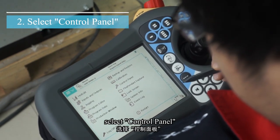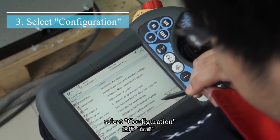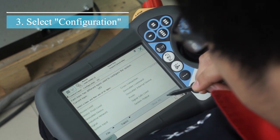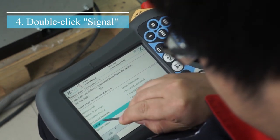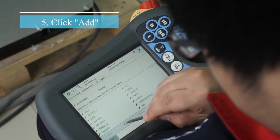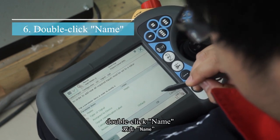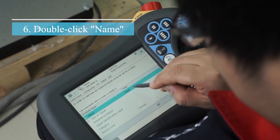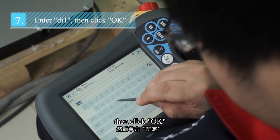First, click the Main menu button in the upper left corner of the FlexPendant. Select Control Panel. Select Configuration. Double-click Signal, click Add, double-click Name, enter DI1, then click OK.